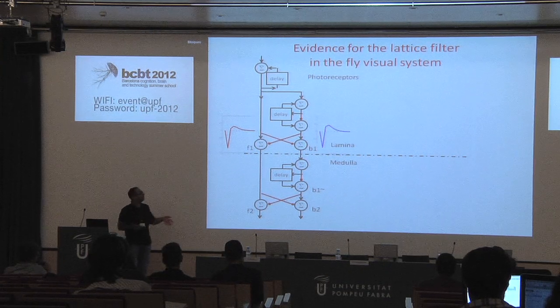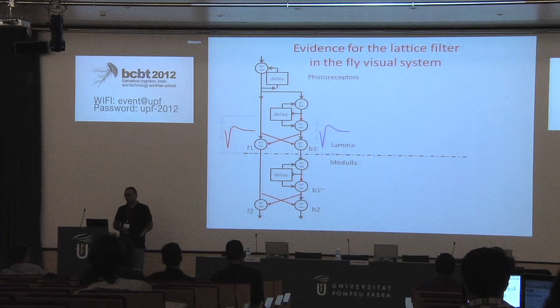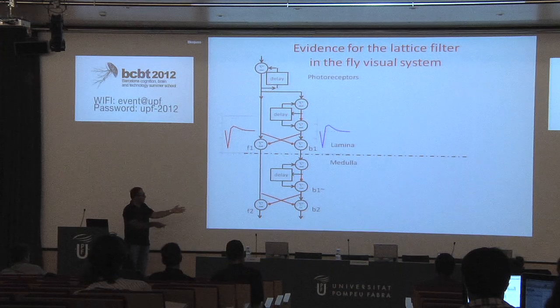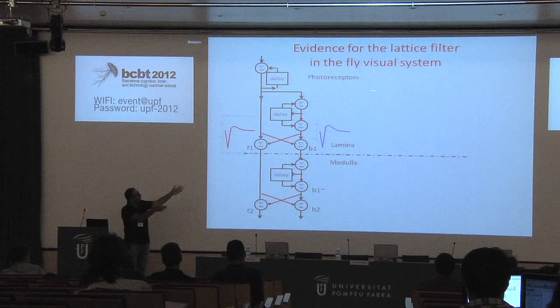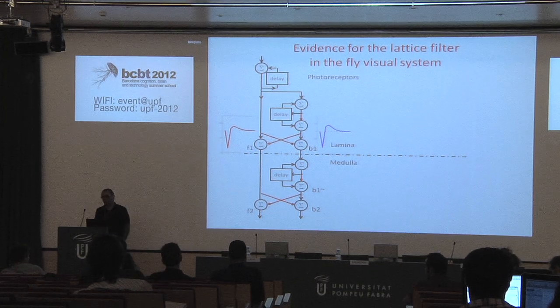I didn't know that. We came to the lattice filter from the perspective of minimizing dynamic range and decorrelation. But when I started reading about the lattice filter, it turns out that that's exactly how they're used, not just for decorrelation, but to generate those features that are put out here and used to predict another sequence, for example.